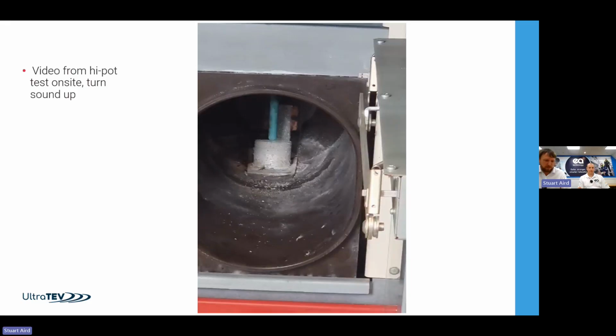A couple of messages in there. Surface activity in general, stop it happening by keeping things clean and controlling the humidity. If you have got it going on and you have got high humidity, before you rush out and do anything else, control the humidity, monitor the activity. You can bring that down, buy yourself some time, if nothing else. And post-flooding, just consider that's something that's becoming more and more topical. We're seeing a lot of questions around these days, unfortunately.